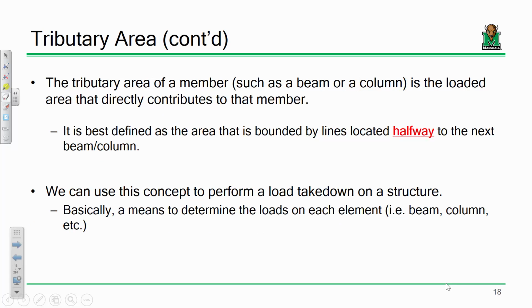comes into play. So I've been talking about tributary area for the past couple minutes. What is tributary area? Well, in a nutshell, the tributary area is the means by which we define how much a given element of a structure is responsible for. In other words, if I'm talking about a floor beam, in this Weisberg Applied Engineering complex there are oodles and oodles of floor beams above our heads supporting the weight of the floor above us.